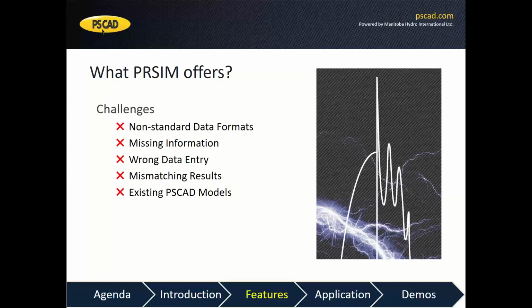We are aware of the fact that users may experience many challenges during the transition to PSCAD. To mention a number of those challenges, we are talking about inconsistency in the format of data files, the lack of vital pieces of information necessary to perform transient studies coming from those load flow platforms, the presence of data entry mistakes in very large databases, which is inevitable, and validation of the translated data in case you face mismatching results.